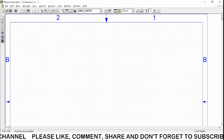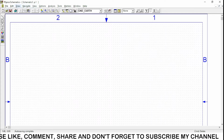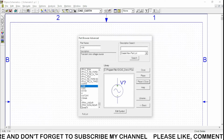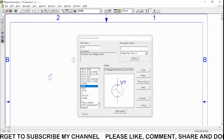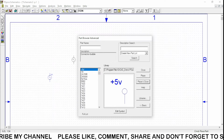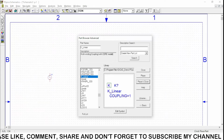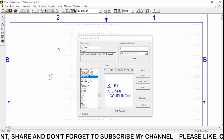To draw the half wave rectifier in the PSpice software, we need to go into Draw, Get New Part. We need a V sine source for creating the alternating current, so I am placing it here. Then we need a transformer. I am going to use this linear transformer type, and I am going to explain how it is to be done. So I am going to place it over here.